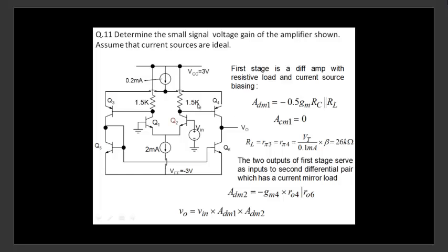At least, I mean, it's more than 10 times higher. So first order approximation, if something is 10 times higher, you are free to neglect it, okay, in the exam. So 26K, 10 times higher, you ignore it. So you have only 1.5K, and you know ADM1.